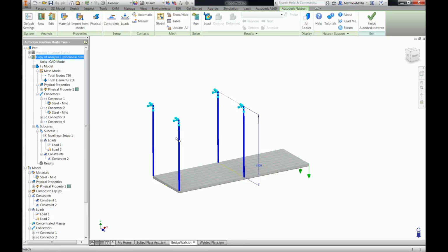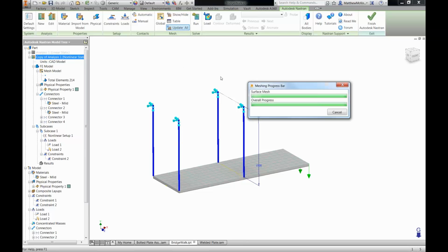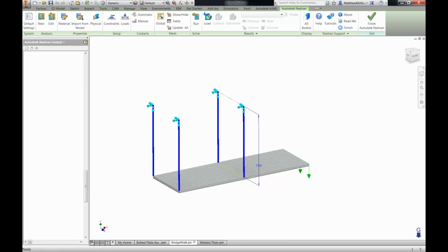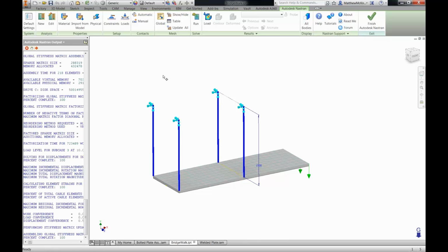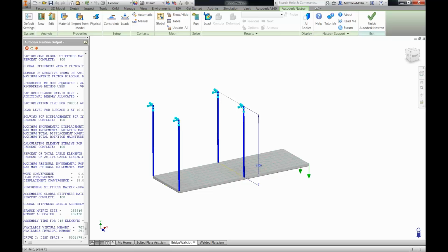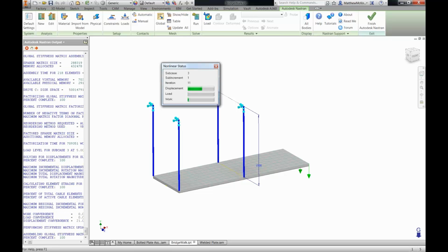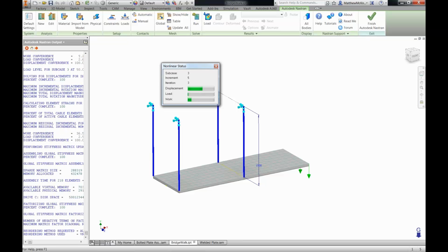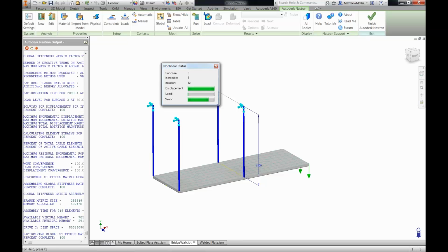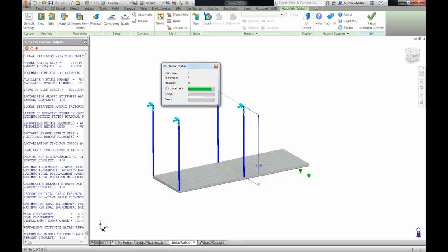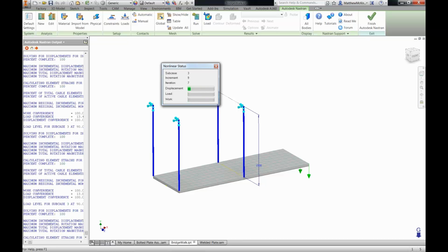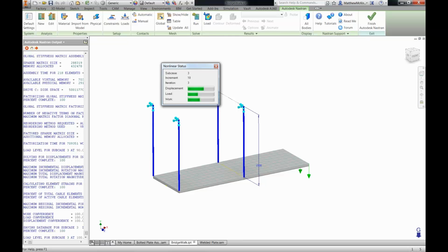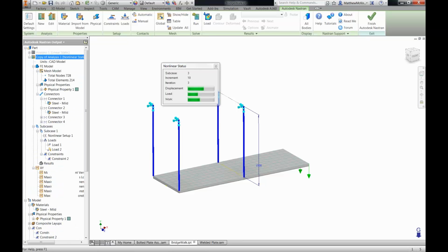I've updated the study. I'm now just going to make sure that our mesh is up to date and hit run. Now you will see that this will take quite a bit longer than our previous study to run, because it's effectively running multiple times over the same study that was run previously, adjusting K-factors and remeshing and reanalyzing our structure, taking into account the displacement and deformation that the part is undertaking as the loads are being gradually applied.